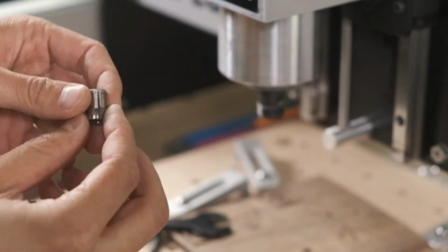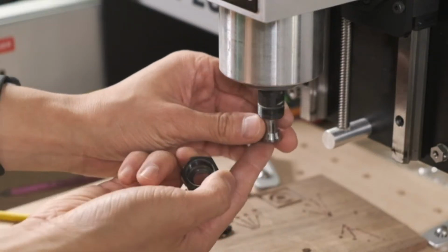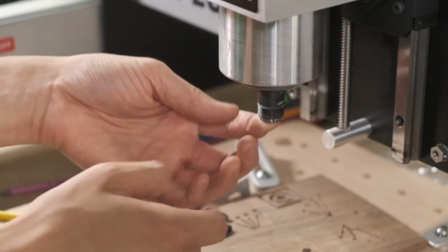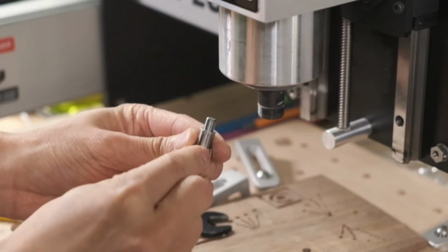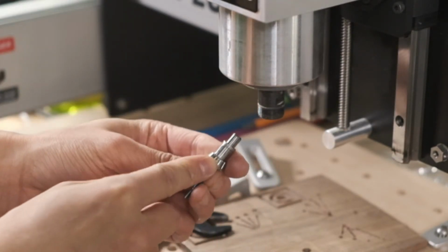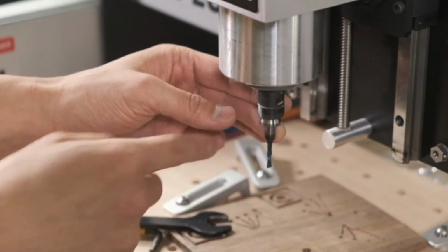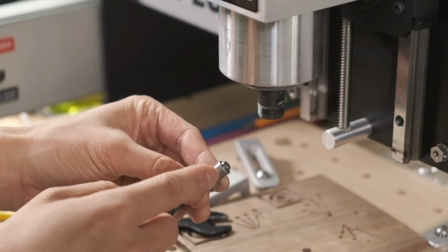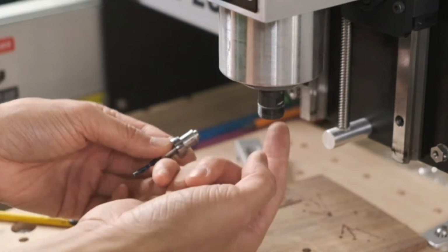And as you use the collet nut, the collet nut forces the collet into the shaft, and that action centers the router bit. And so if the interfacing surfaces aren't clean, that dust will push the collet off center, and you're going to get more runout. So if you want, just take a clean cloth, maybe a little isopropyl alcohol, wipe down these surfaces inside and out.